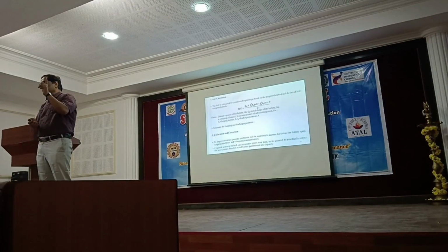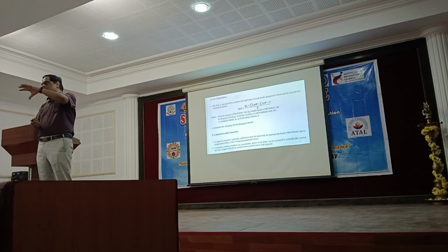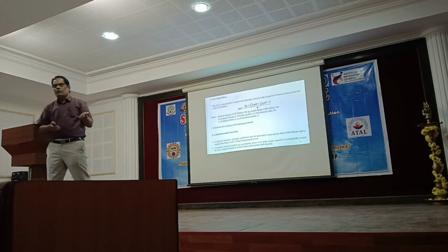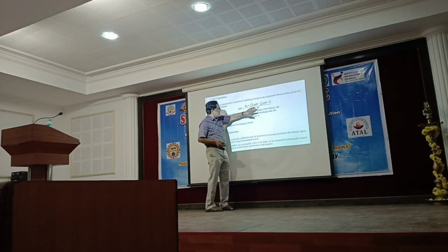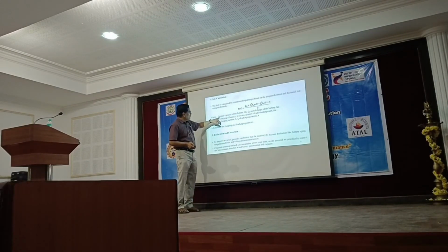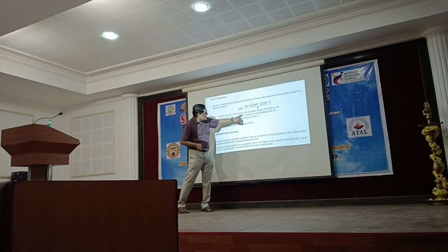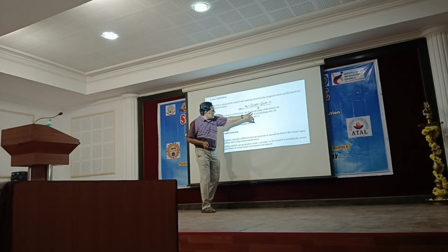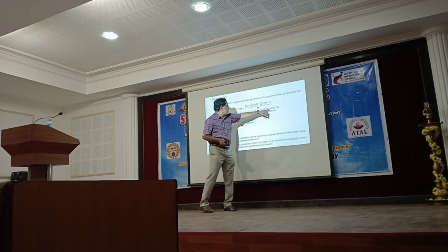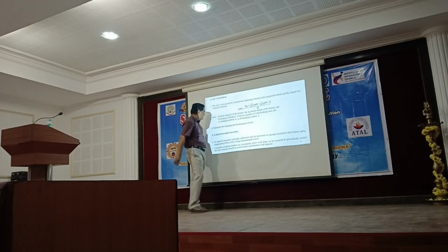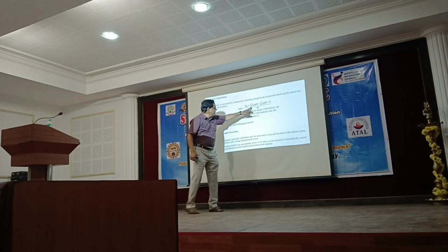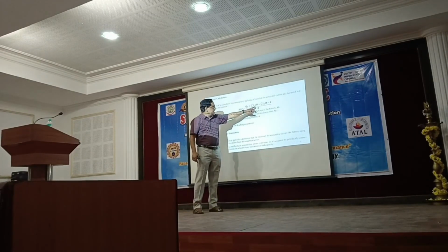I already showed the Butler-Volmer equation. Before that, I'm just building up what is SOC and what formula is used. I mentioned Coulomb counting. What is the formula you have here? Q is nothing but the rated capacity of the battery in ampere hour, and Q0 is the initial charge of the battery in ampere hour. And what you are trying to monitor continuously is the integral. What is this? This is the current. Eta is the over voltage.